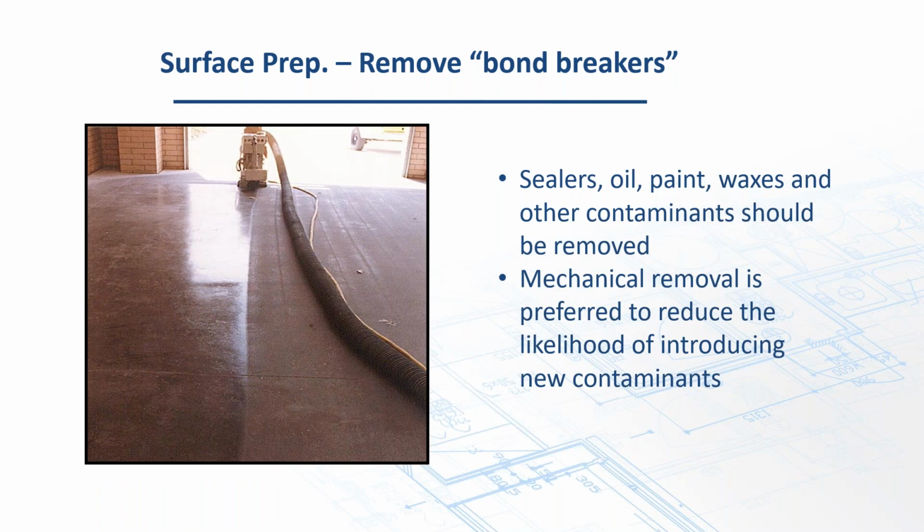Make sure that contaminants on the slab get removed. I can't tell you how many levelers I've seen fail because of old adhesive residue. Everything from cutback to just carpet and vinyl adhesives. These materials are very, very strong. They expand and contract in the initial stages a little bit. Again, if they're shrinkage compensated, a very minimal amount, but if they're overwatered, they're going to do it a lot and they're going to fail.